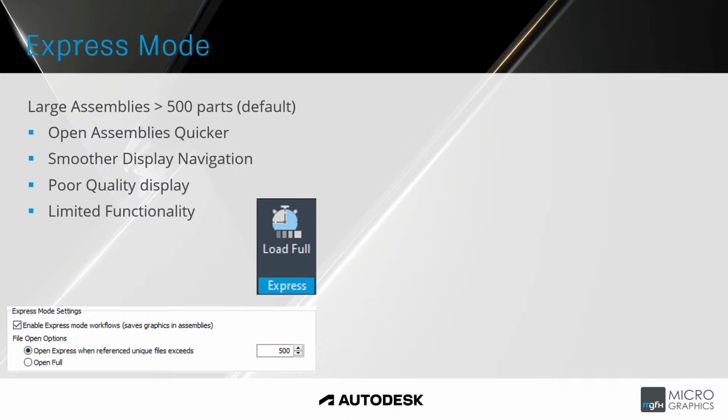Now I've got there the load full icon. I'll show you where that is in Inventor once you load in Express mode. Also below that, we see the Express mode settings. You can see there, open in Express mode when the unique files exceeds 500. You can set that default option to open full, so every assembly will open full when you open it.